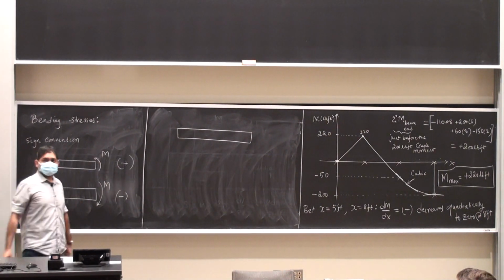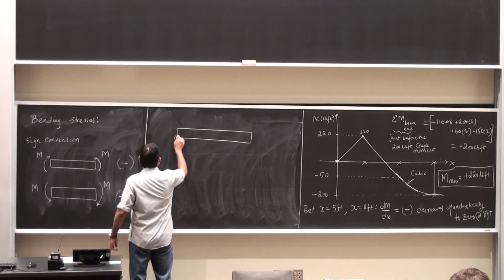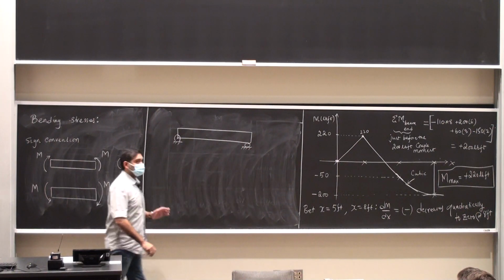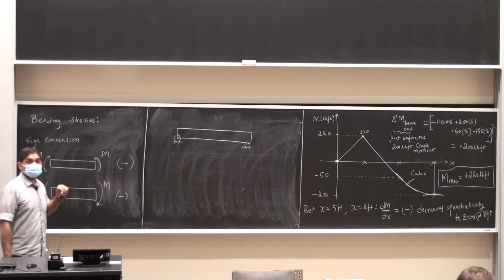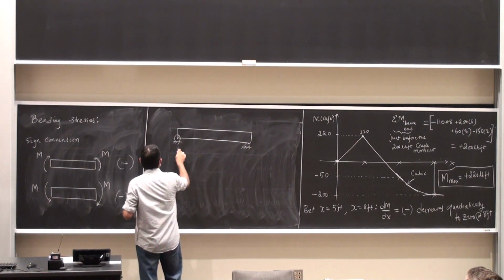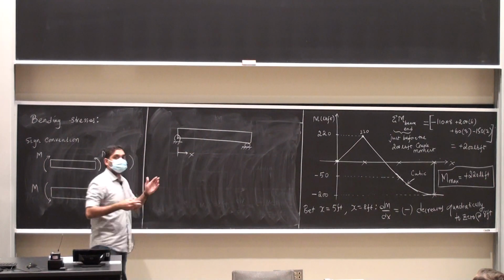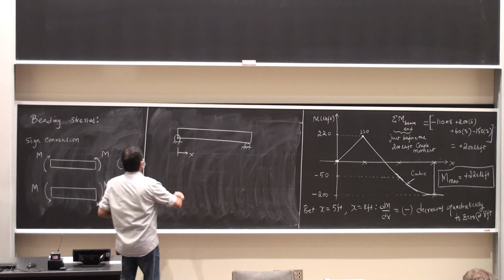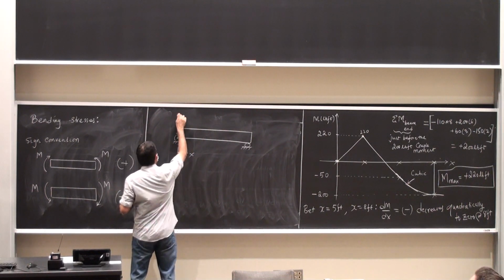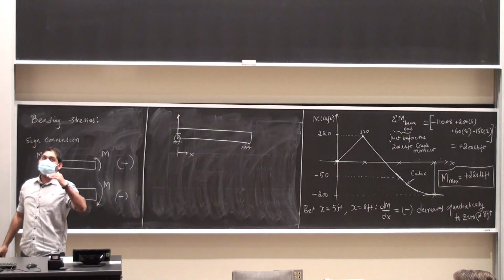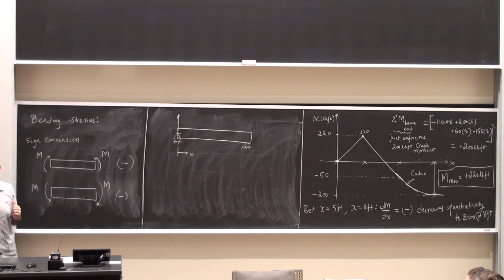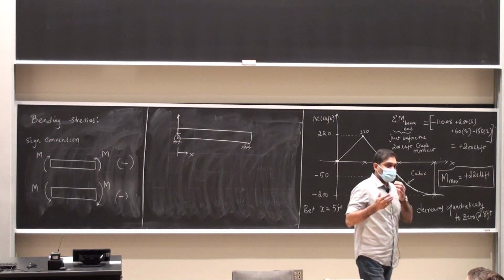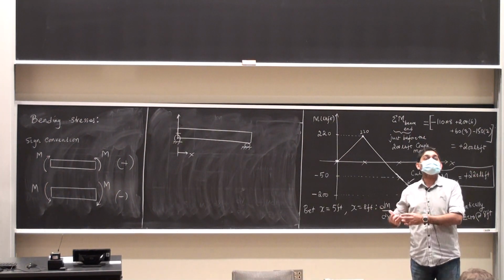Let's say that I have a simply supported beam. First thing is x along the x-axis, starting from left to right. That's a typical notation. Y along the y-axis. Watch this. My y value is going to start from the centroidal axis. In statics, you would have learned about centroids and moments of inertia. The use of the centroids is going to come into relevance now.